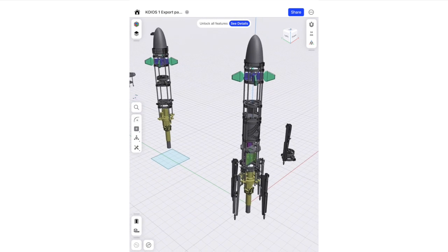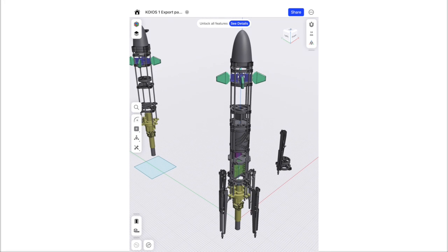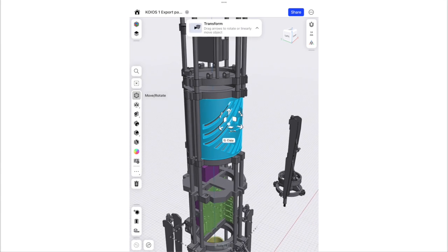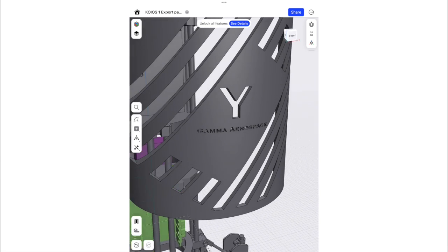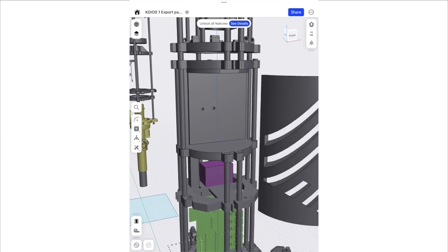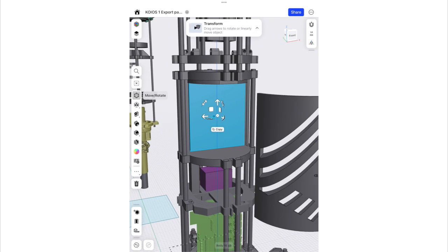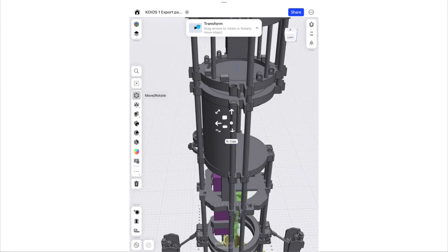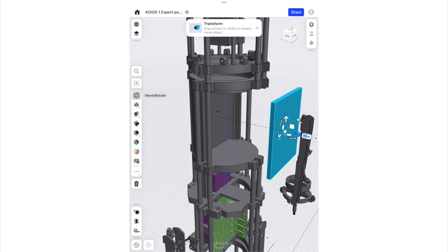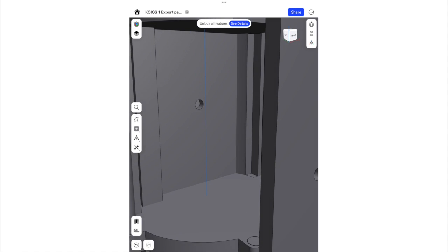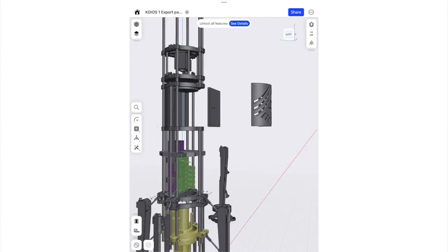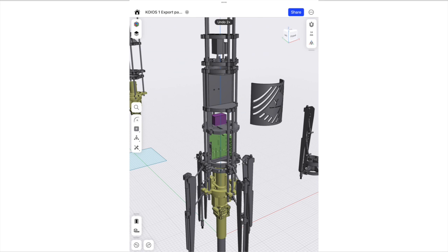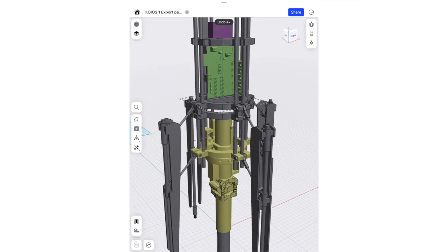Then we have, as we go on to this system here, the slightly more developed system for KOIOS I. We have the parachute bay, which has a piston here that comes out and pushes a parachute that would be in this compartment here, pushing out this cover here. As that cover flies off, we have a parachute that can deploy, maybe a drogue chute that pulls that parachute off for safekeeping, and we can ensure this vehicle returns safely to the ground for extraction of data.